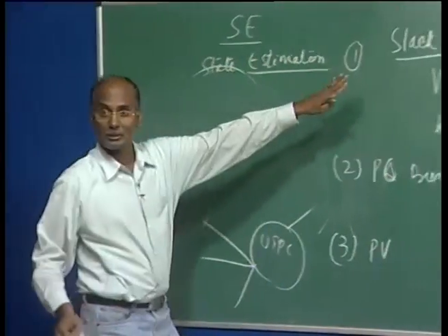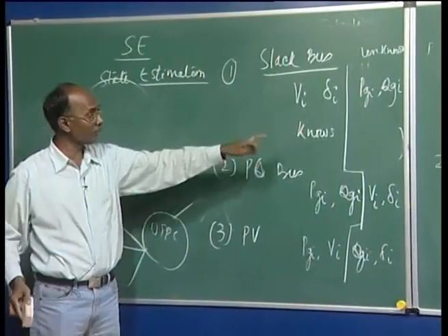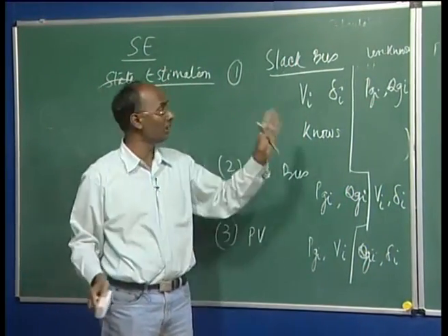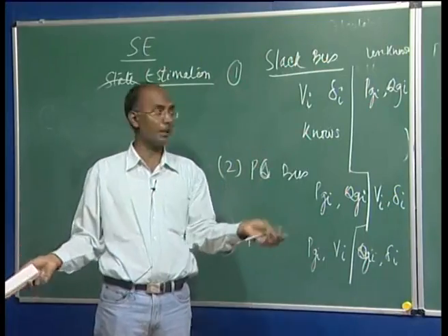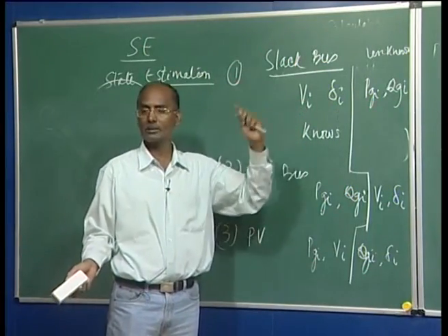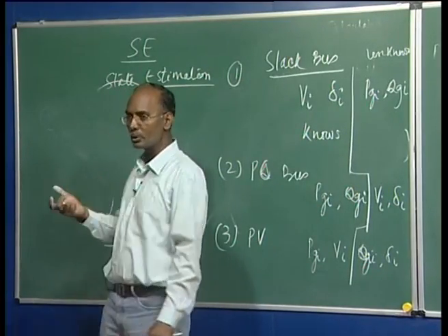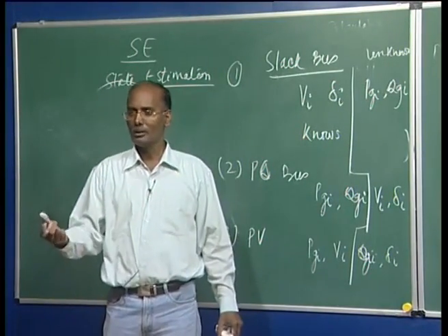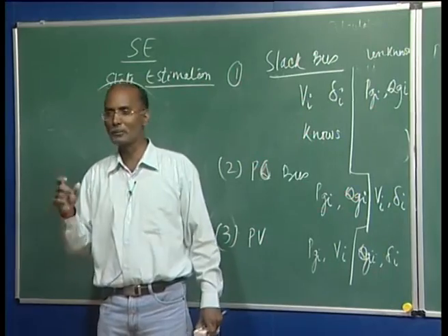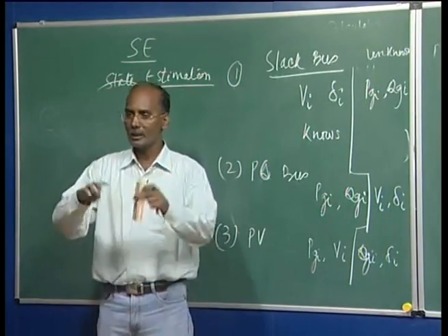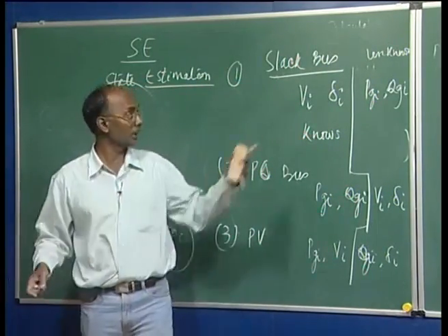So this is something different from this. Here we are not worrying about the frequency; we are assuming the frequency of the whole system is the same, and here the voltage and angle we are setting. For infinite I also said V angle 0. Zero you can put, or you can put any value. So this is also sort of a reference bus, but it is not treated in the sense of which I am talking here.